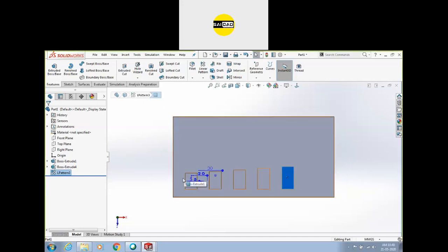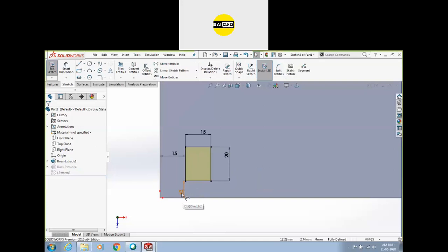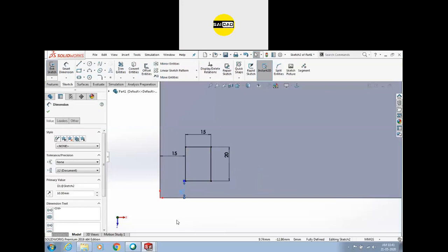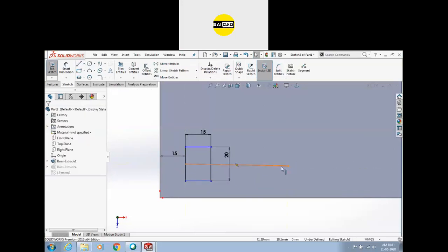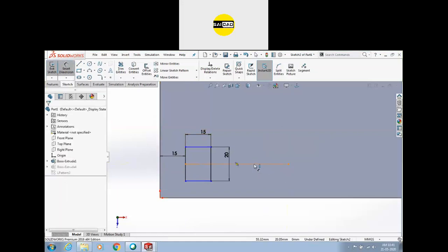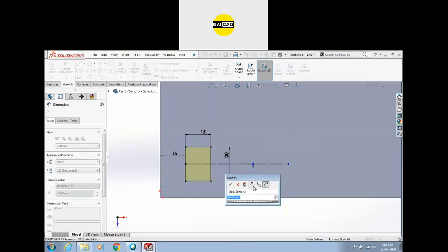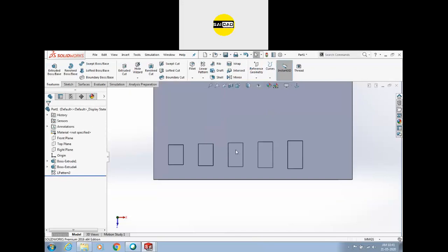Because we have applied a value here, we have not created this object symmetrical. We have to make it symmetrical, so that we can do that. Go to the drawing, and you can see we have applied a distance 10 here. So this 10 will be there. Okay. If we delete this 10, create a line from the mid, like this one, convert, and define the value that this should be 25. Exit out. Now you will see it is increasing in both the directions.